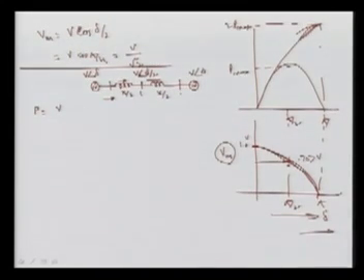So I can write V square upon x by 2, this section, into sine delta by 2, or I can write 2V square upon x sine delta by 2. So now this is the power flow expression, and if we draw the characteristic of this expression, what is happening?